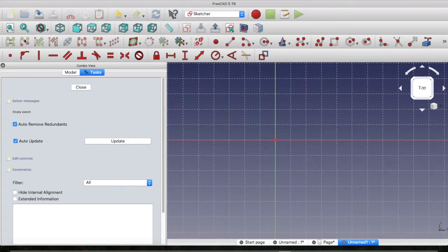On the third band from the top of the toolbar, we can see a package of tools for our use. For making the 2D sketch of our intended pad, we have to first make a rectangle of 100 mm length and 50 mm width. We can use either the line tool or the polyline tool.